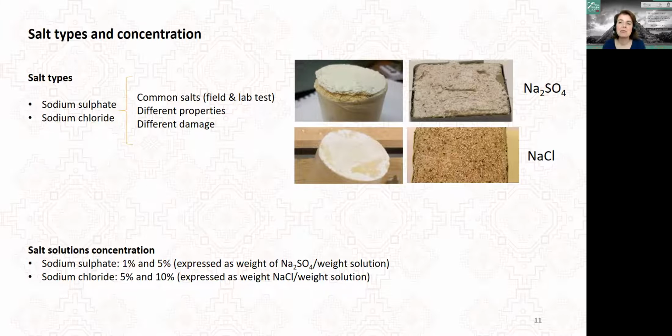For example, groundwater can be considered a diluted salt solution. And the amount of salt which will accumulate in the stone will depend on the absorption and drying behavior of the stone. Also, using a constant salt solution concentration facilitates the procedure, so it increases the feasibility of the procedure. We decided to use 1 and 5% concentration in the case of sodium sulfate, and 5 and 10% concentration in the case of sodium chloride.